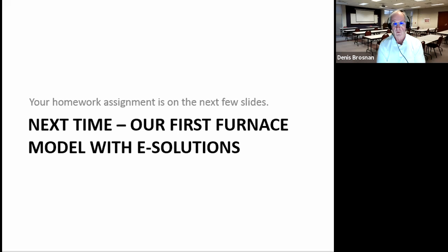There are other types of mortars that contain phosphate binders or clay binders. I understand that, but that's something to be certainly aware of. I talked a little bit about respiratory hazards and respiratory protection with ceramic fiber. I talked about heat storage and heat conduction in furnace and multi-component linings. Particularly, I talked about not exceeding the duty rating at any portion of any component because that's going to cause deterioration or shrinkage in the refractory.